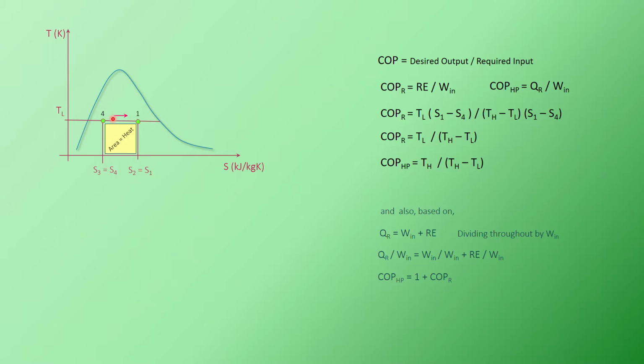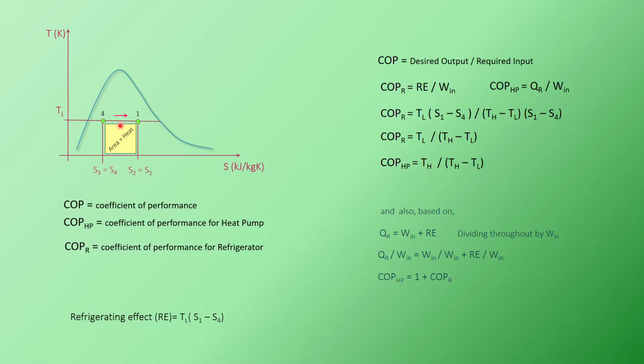That shows there's an increase in entropy, so some heat energy has gone into the system. That means the refrigerant. So that would be the refrigerating effect, heat absorption or cooling effect, by the refrigerant. The area bounded by this will be equal to your heat absorption or refrigerating effect. Okay, so RE equals the height multiplied by the base. So here, the refrigerating effect or heat absorption.